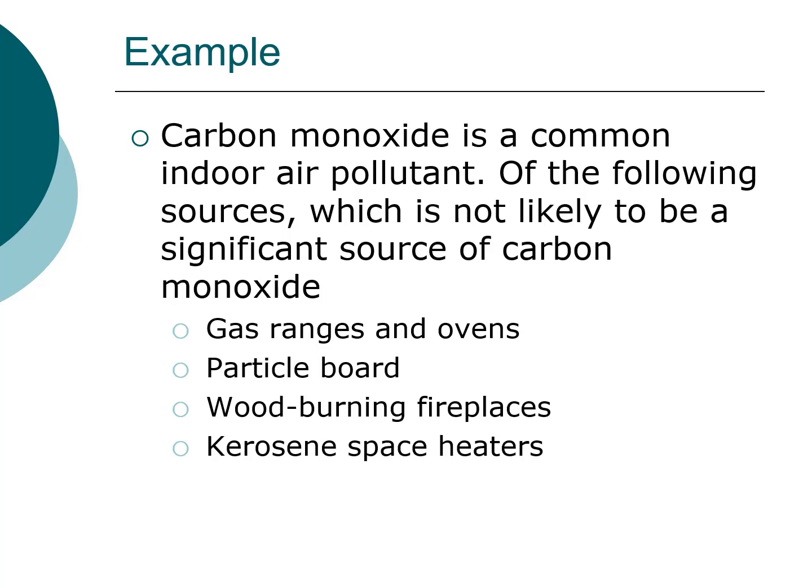So in this question here, again, another recall type question, you're told carbon monoxide is a common indoor air pollutant. Of the following sources, which is not likely to be a significant source of carbon monoxide. Important thing to remember here is that carbon monoxide is released by incomplete combustion, so it's a product of combustion. So if you look, gas ranges, ovens involve combustion, wood burning fireplaces involve combustion, as do kerosene space heaters. So the answer is particle board.